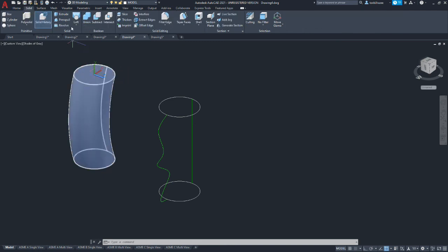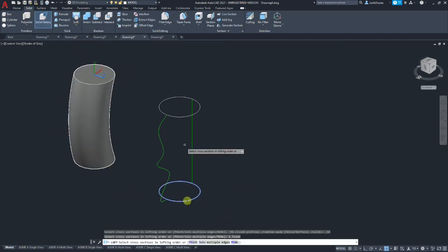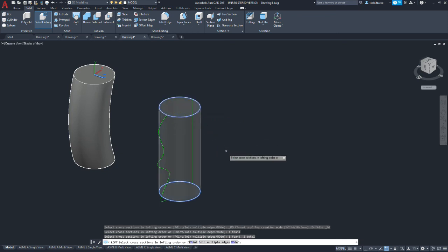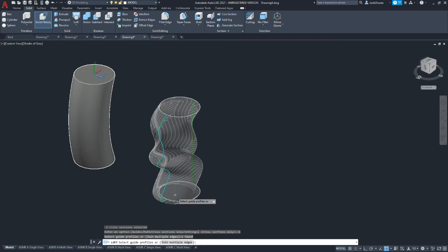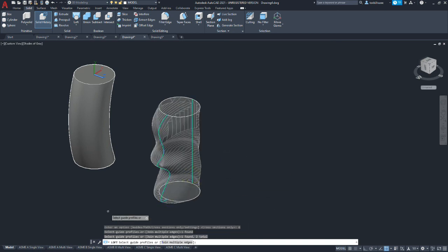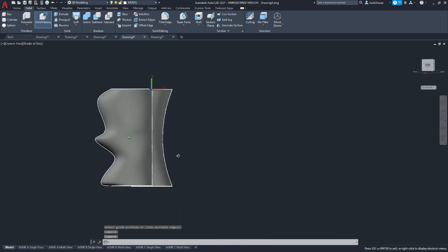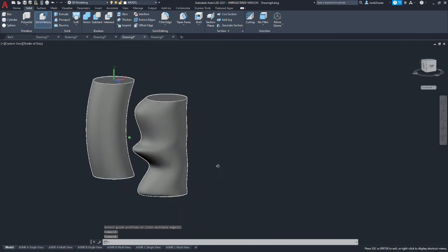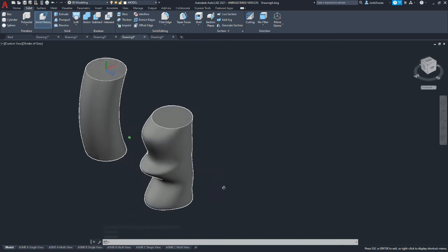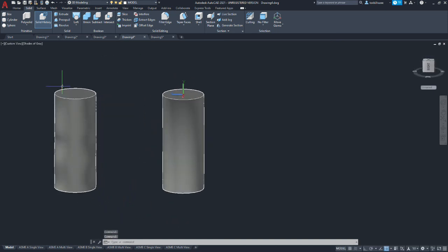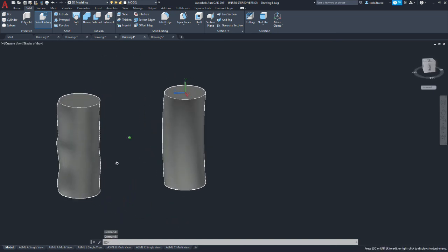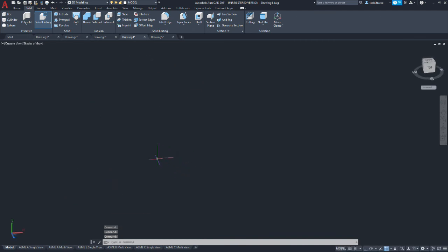Now let's do the same thing to this other one here. Go to Solid, Loft, select our two sections. We're going to accept that selection and we're going to select Guides instead of Path. Now we need to select our two paths and we get a preview here and hit enter and I get this weird Mobius looking thing here. So the section right through the back here should be a straight line and then it blends between the two.